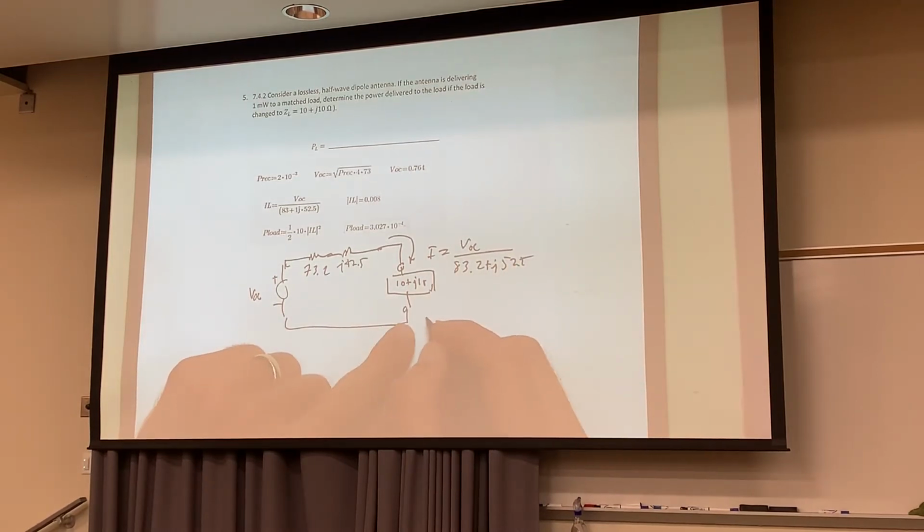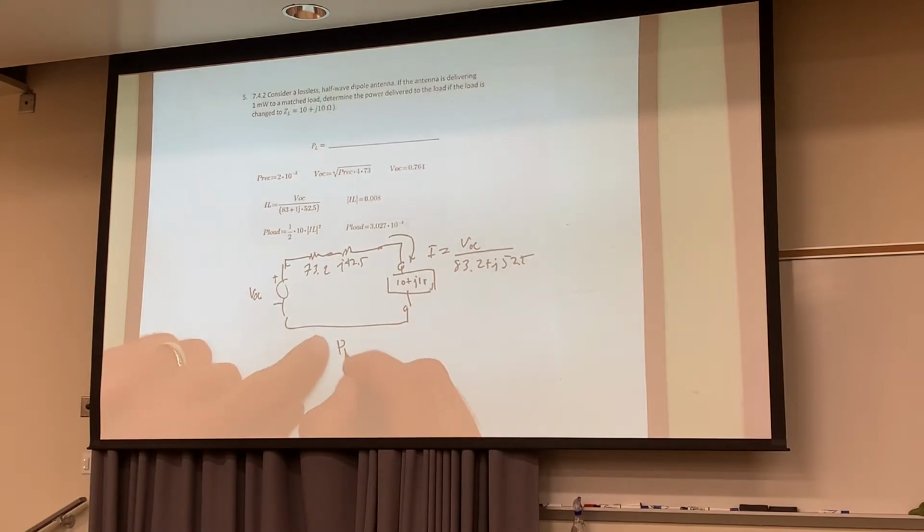And then to get the P received by the load, P load, that's simply going to be 1/2 the magnitude of that value by magnitude, you don't put a j in there, divided by 10, because the only thing that burns real power is that 10 ohms. The j10 does nothing, that's reactive power. So you just divide it by 10. Correct, class? Remember that. You'll see this again.